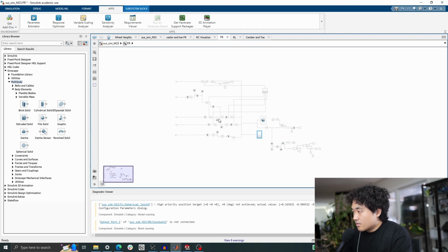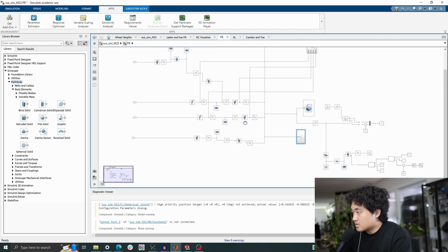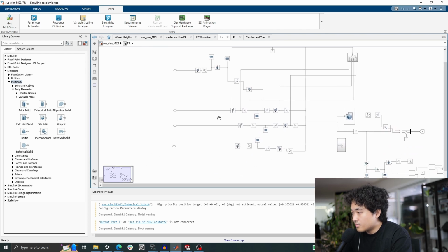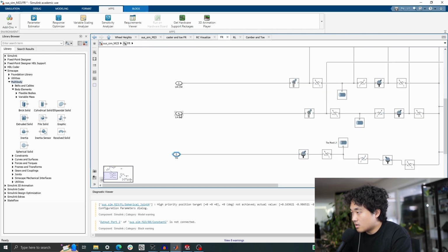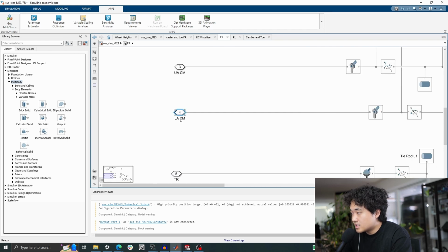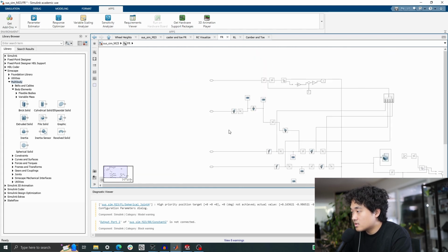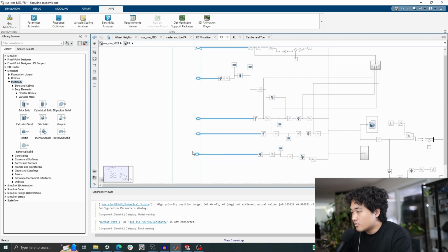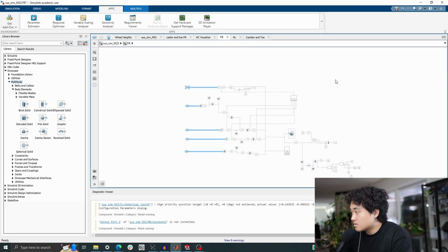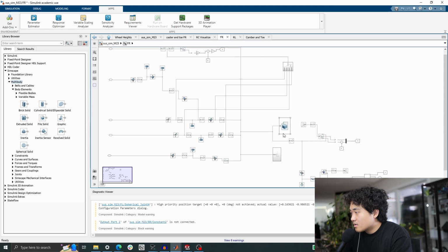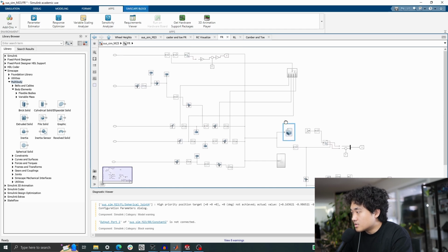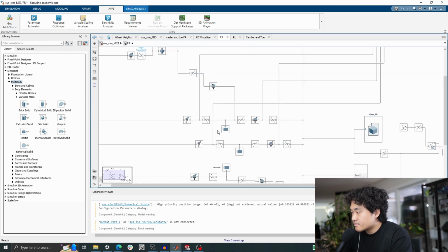Alright, let's go into the front right system. Looks a little complicated, but if you go in closer, these are... So LACM, for example, is the lower arm chassis mount. This is upper arm chassis mount. Here's a tie rod. SH is shock chassis mount. So this is inboard, if you didn't already tell. There's a wheel. I made it a little bigger so you could see it better.